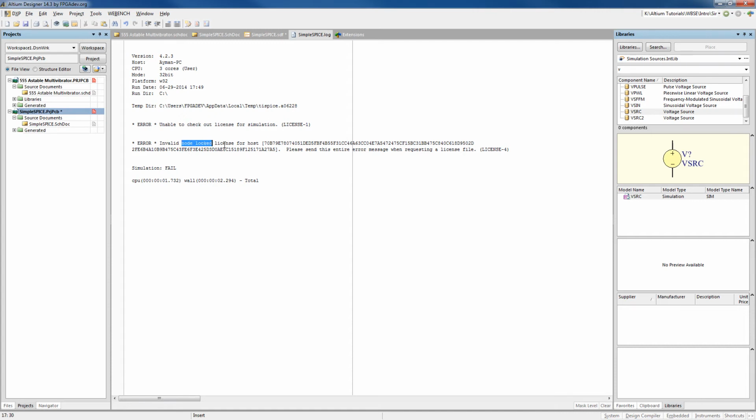So what is it saying? Well, the problem is that now we need to get the license for this in order for it to work. So Altium has the connection capability to the Webench, however, it just doesn't have the license for it. And this is actually really important because you need to take this log file and mail it off to TI. And so the question you may have then is, well, okay, that's fine. Where is that located? All right, so let me bring that up over here on this other side.